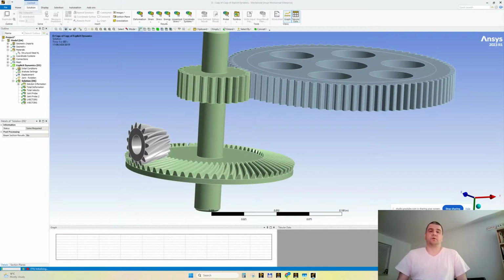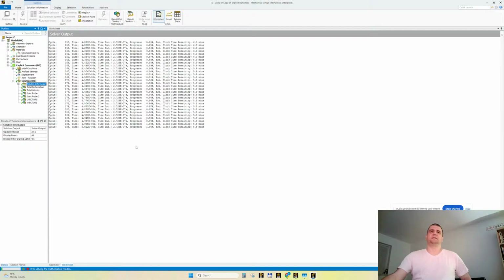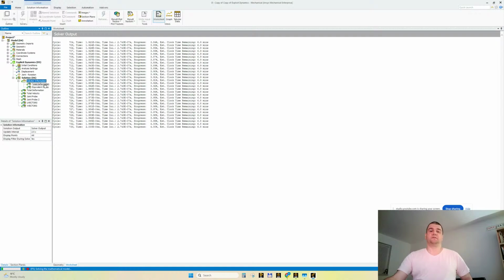Bonded contacts ensure convergence, even though it's stupid and useless. And this is where the line is drawn between advanced people and beginners. The line is drawn when using exclusively bonded contacts, then using frictionless and frictional.